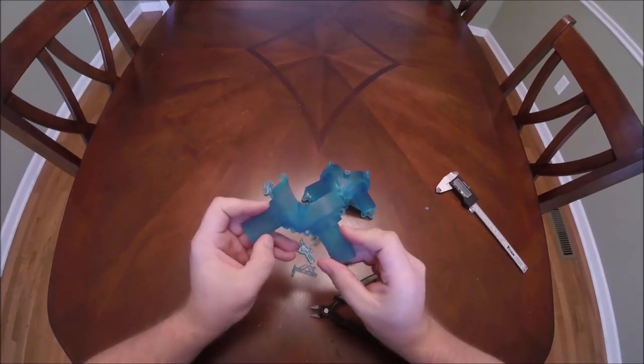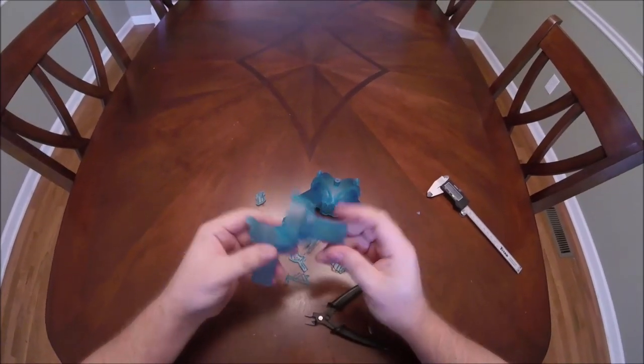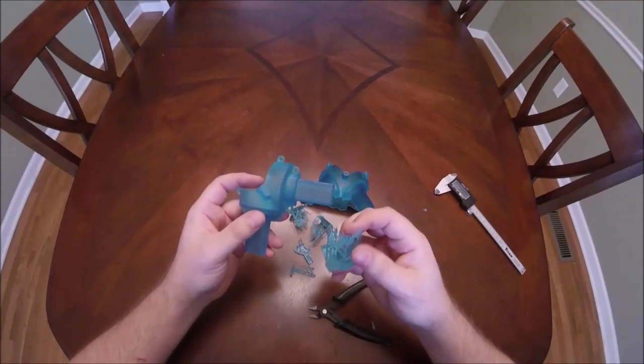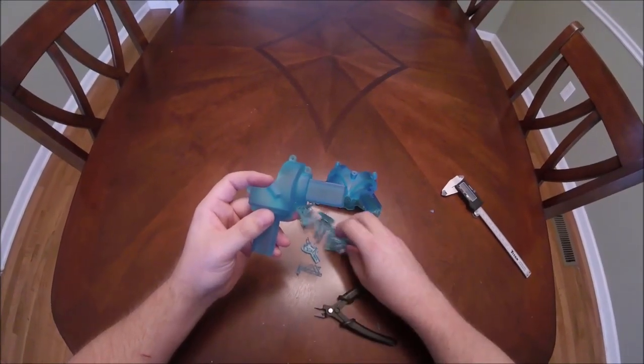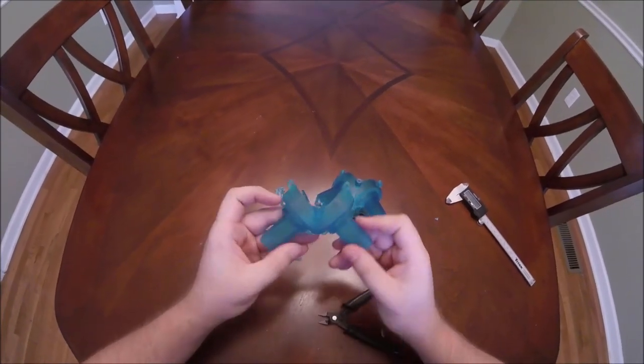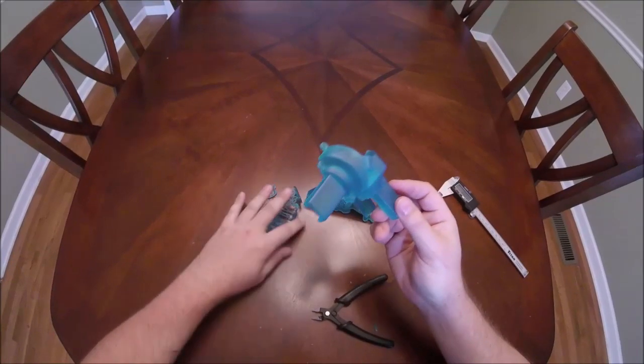But overall, you can see really when you fine-tune your support structures, I used about, I think I used 0.55 millimeter supports on this part at a 0.9 density. As long as you're not way over supported, the supports come off the parts really easily.